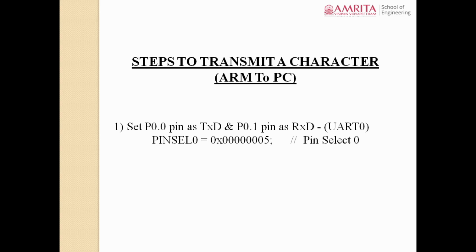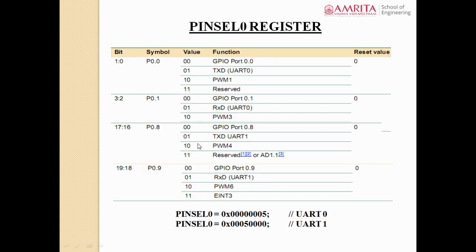If you want to configure the functionality of P0.16 to P0.31, you should use PINSEL1. But now we are configuring only P0.0 and P0.1, so we are using PINSEL0.